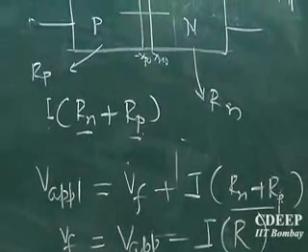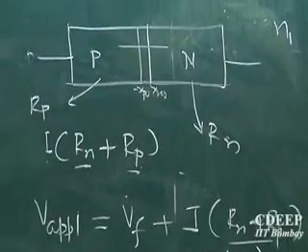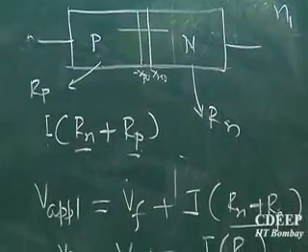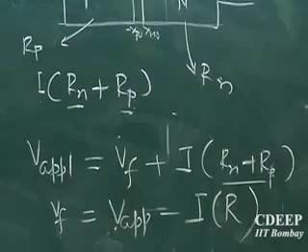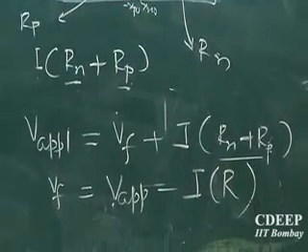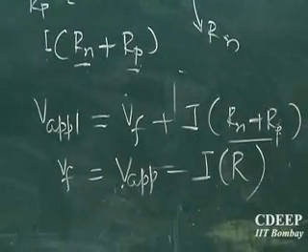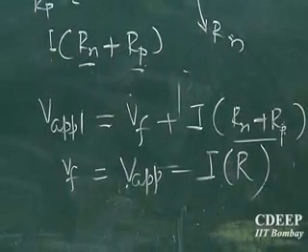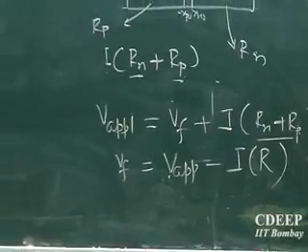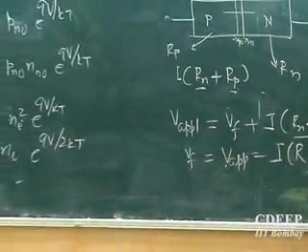But the number of carriers at higher biases is increasing, it will be very high, you are crossing even high injection levels. So the carriers on both sides may be almost equal, in which case it will not act like a junction, but it will act like a simple resistor. So you see an ohmic region at the end of it.